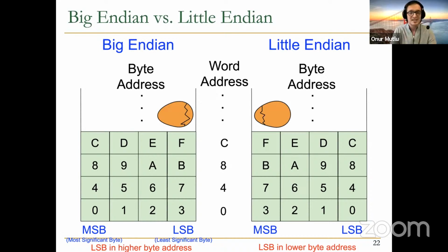This really is, again, specified by the instruction set architecture. So let's do 2 examples over here. So this is the big endian example, which is not MIPS, not LC3B. Basically, big endian means that you have 4 bytes in a 32-bit word in MIPS, right? You have one is the most significant byte, which is the most important byte. If you represent this 32-bit value as a number, that's essentially the most significant one. And another is the least significant byte, right? That's basically the lower order bits.